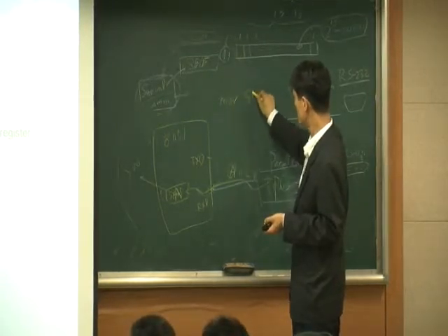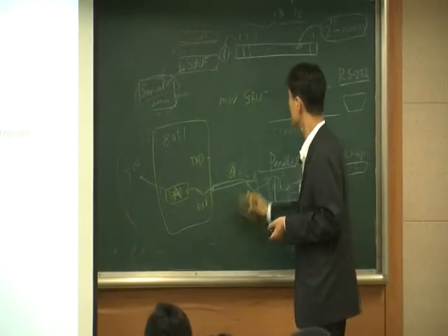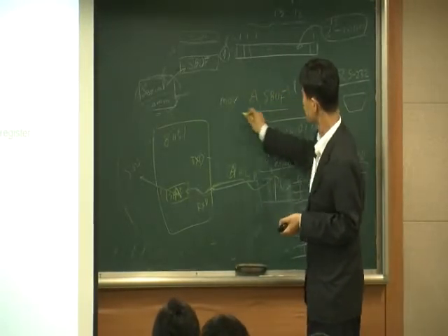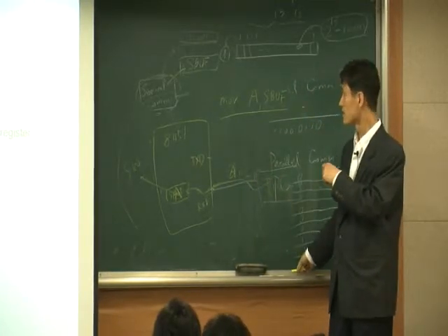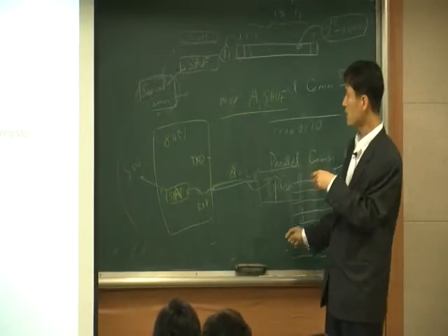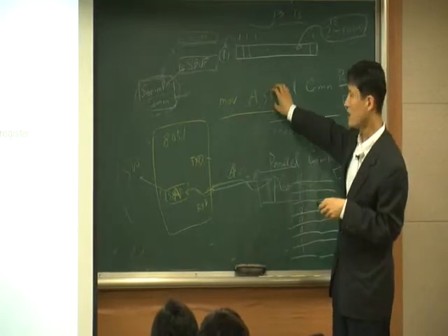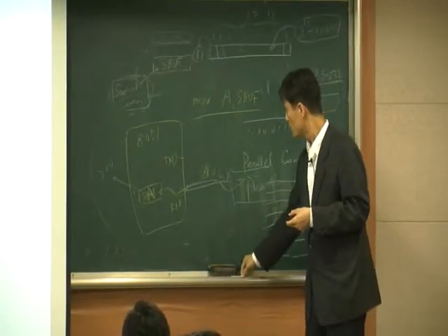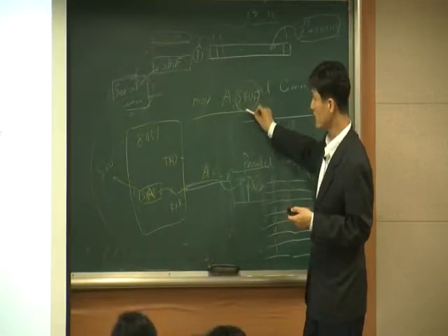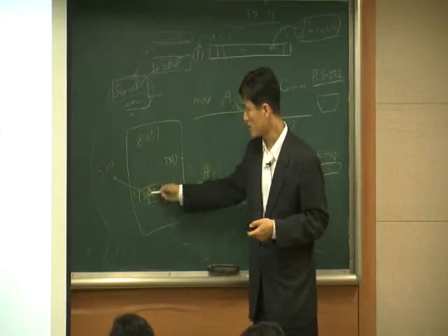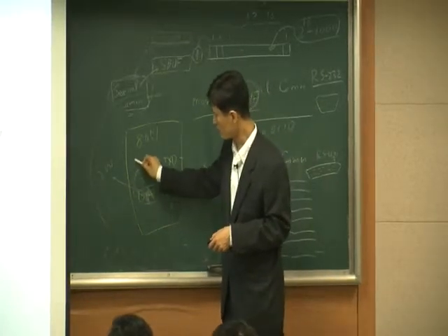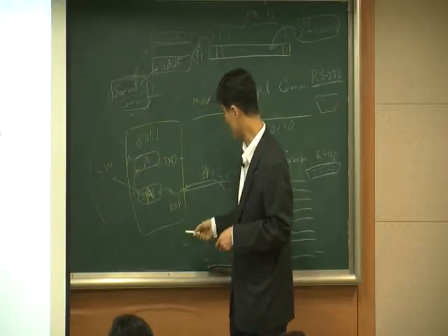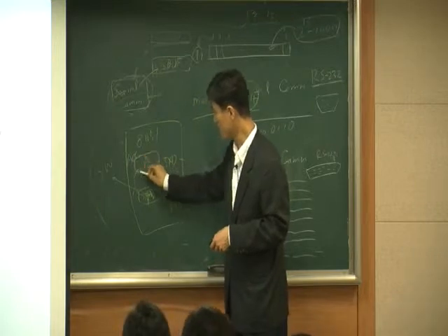Reading it out basically means you can do it like this. What is this? This basically means that you are copying the value in SBUF into A. That's what I mean by reading it out. So you copy the value inside here, A in this case, into A, the accumulator.